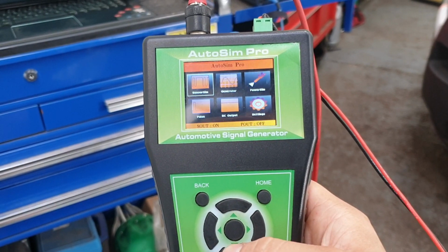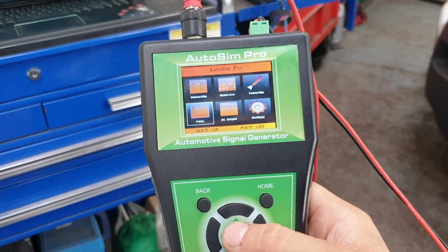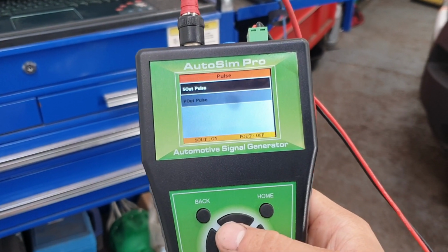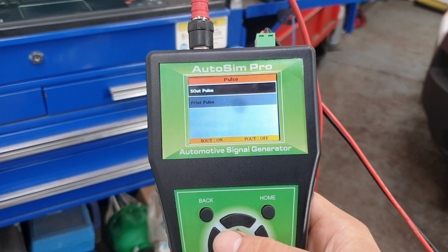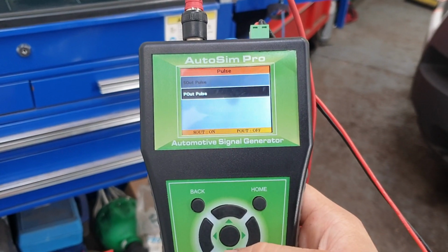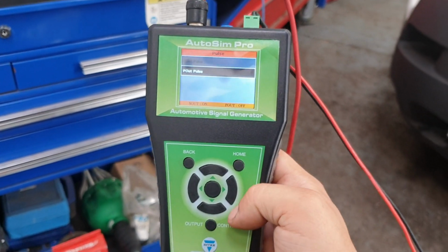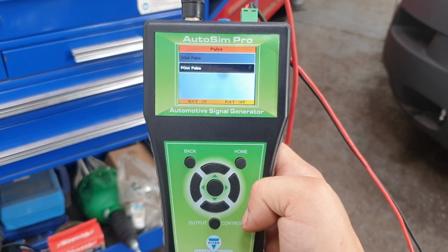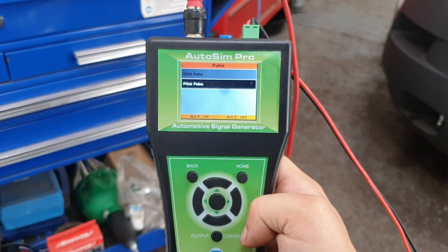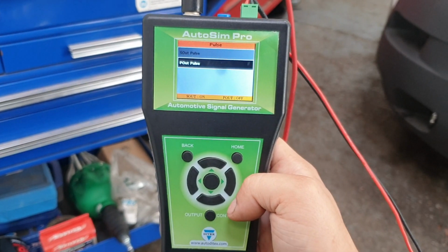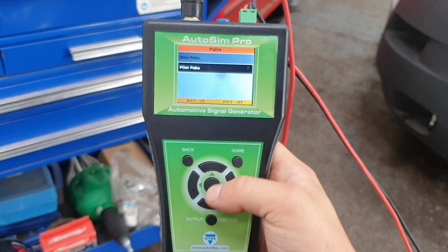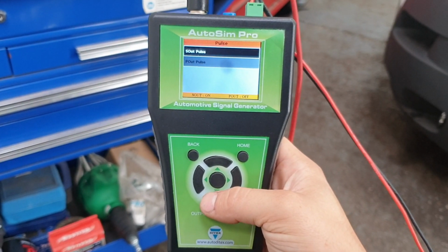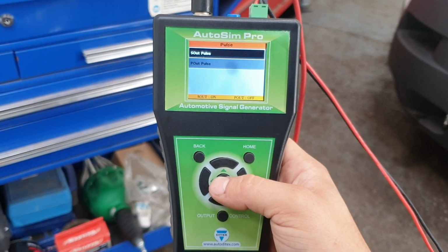We do have a pulse option. So this will send SOUT, which stands for signal out pulse, or you can do a power out pulse. What it can basically do is send a power output using the output of the driver, which is 4 amps maximum output on this mode, or we can do a signal output, which only sends a maximum of 150 milliamps output. So we can go into this one.